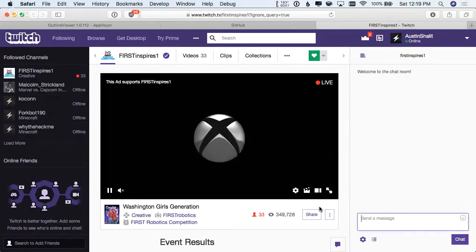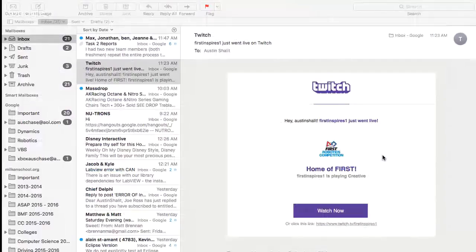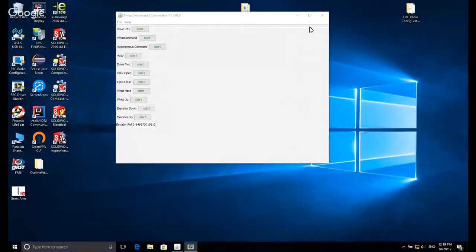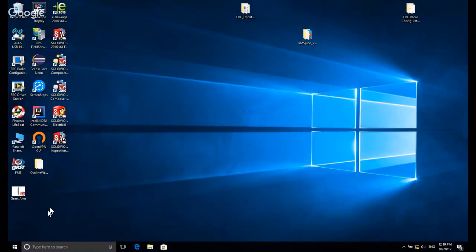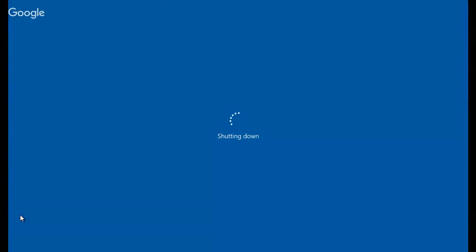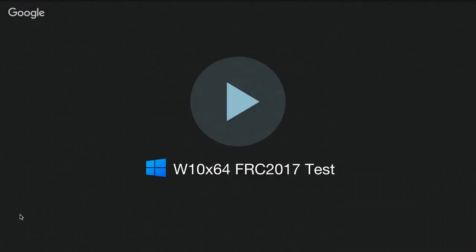So the Pixycam is a great camera to try, and if it works for the game, it's pretty straightforward. And then do the trick where you use the ring light. Yes, that's the only way to do it. And then you turn down the camera sensitivity way down, so all you see is really bright. It seems really clear.